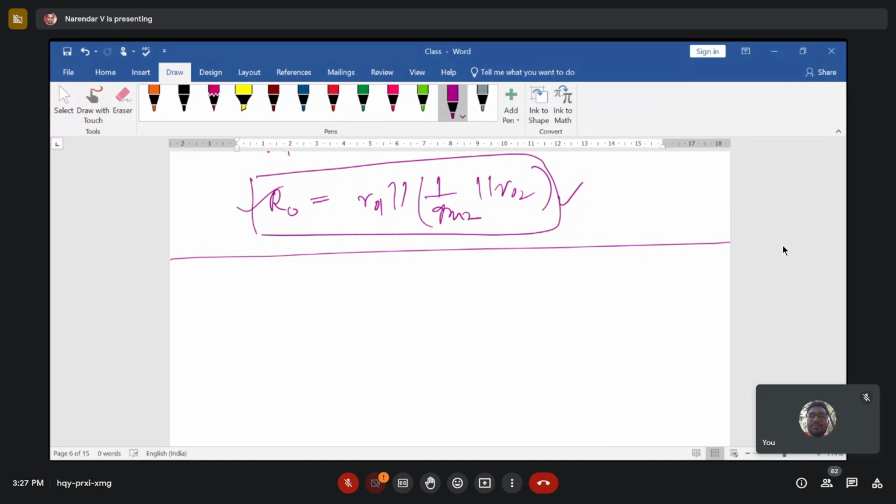So far we have been discussing how to boost the gain of an amplifier, and we had seen the common source stage with resistive load, and this resistor replaced with a diode connected MOSFET. And we had seen the gain as well as input resistance and output resistance of a common source amplifier, right? Now what we try to do is take a different load element instead of the resistor and diode connected load, and see how the gain is going to be modified. Okay?